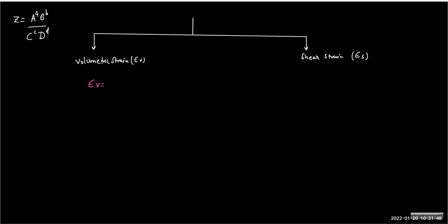By applying pressure or force, we generally tend to compress the body. We don't try to elongate the body. And by definition, we write it as such because it is generally compression. Bodies can be compressed, but it's difficult to increase the volume of a body. So the volumetric strain turns out to be the change in volume upon original volume, you can say minus dV by V.